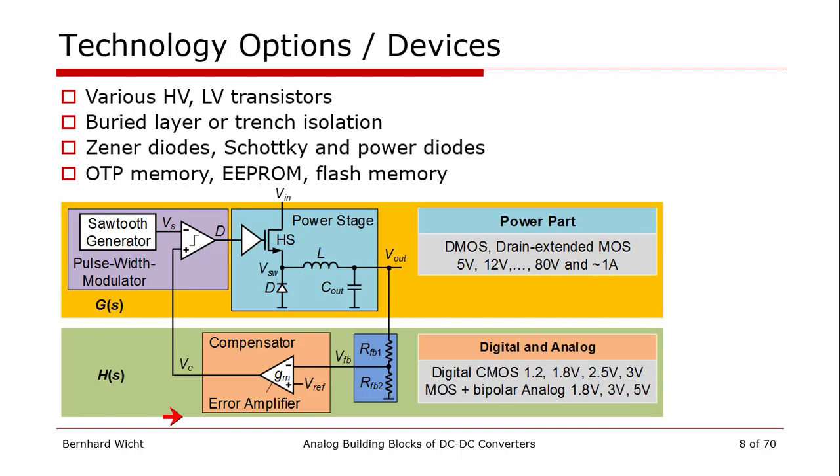The design of these blocks is closely related to the technology options. So we've got a variety of low voltage and high voltage transistors, in addition to various isolation capabilities, buried layer isolation, trench isolation. And on top of that, various components like Zener diodes and Schottky diodes. And there's also non-volatile memory available. So, that helps us to implement these DC-DC converters for various applications.